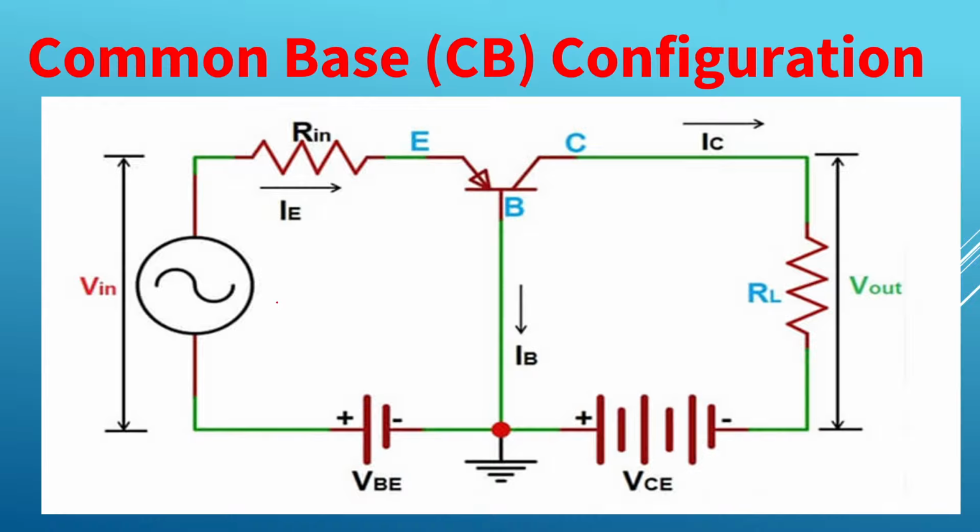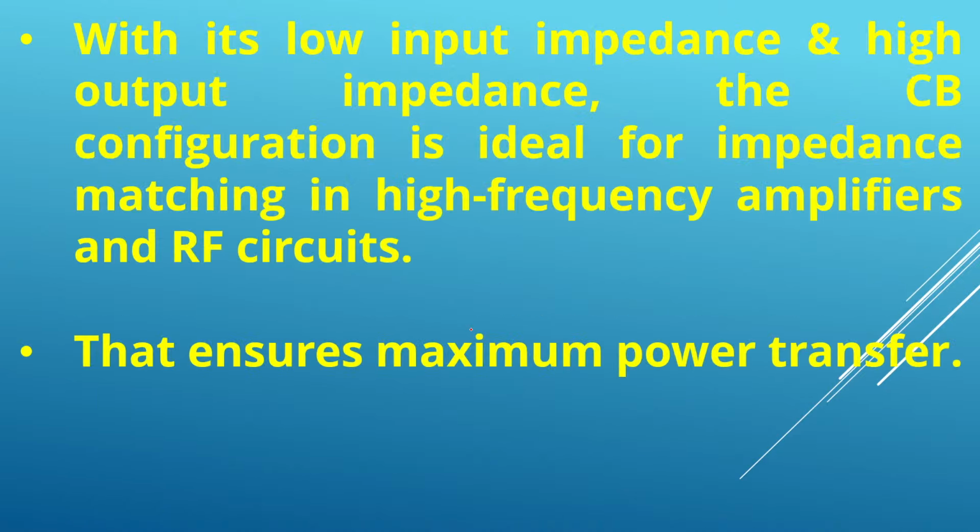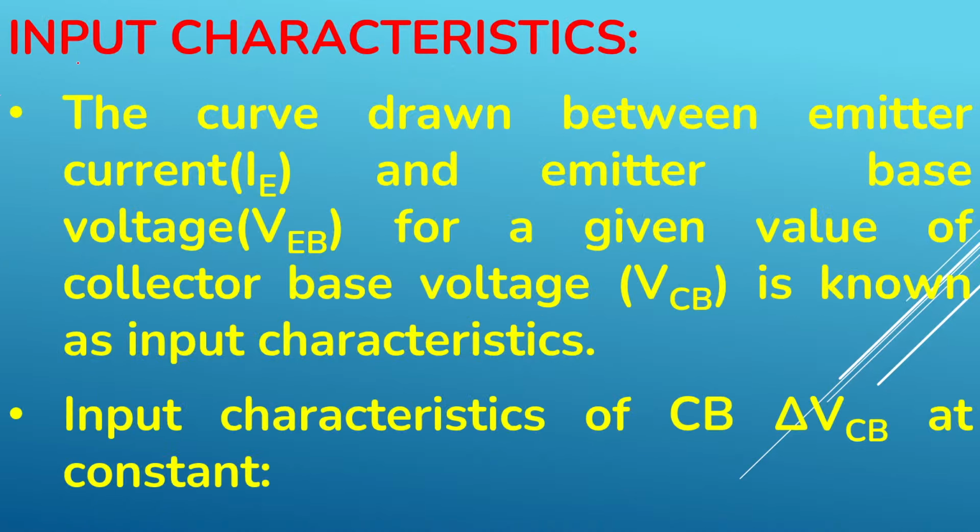These sorts of circuits are ideal for impedance matching in high frequency amplifiers and radio frequency circuits. This sort of common base circuit ensures maximum power is transferred from the input to the output. Now let us see the characteristics. Let us see the input characteristics.